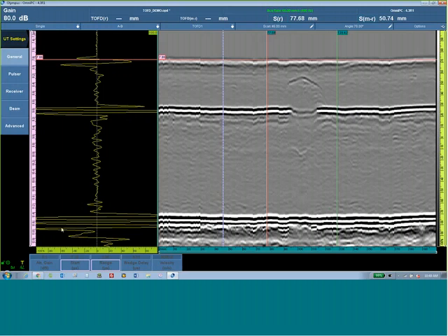Okay, the operator used a database velocity. If I see a series of files from the same pipe that were all acquired with a different velocity, it is a red flag. It is a problem with the work procedure. If the probes are locked into the scanner and you're doing the same series of inspections, there's no reason that the data files would include a different velocity.